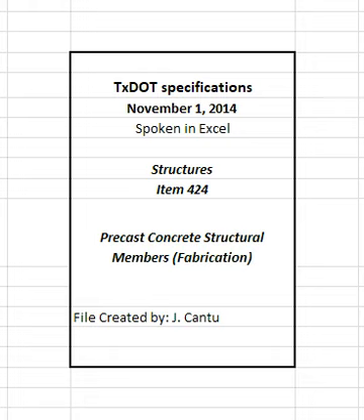4.2.5 Placing concrete. Place concrete only when its temperature at time of placement is between 50 degrees Fahrenheit and 95 degrees Fahrenheit. Take responsibility for producing quality concrete under any weather condition and ensure adequate weather protection provisions are on site and available for immediate use. Provide immediate protective measures without compromising the quality of the product if rainfall occurs after concrete placing operations have started. Failure to immediately provide adequate weather protection may be cause for rejection of the affected product.